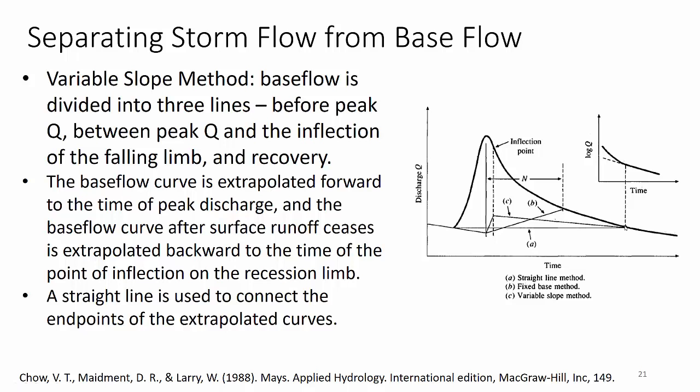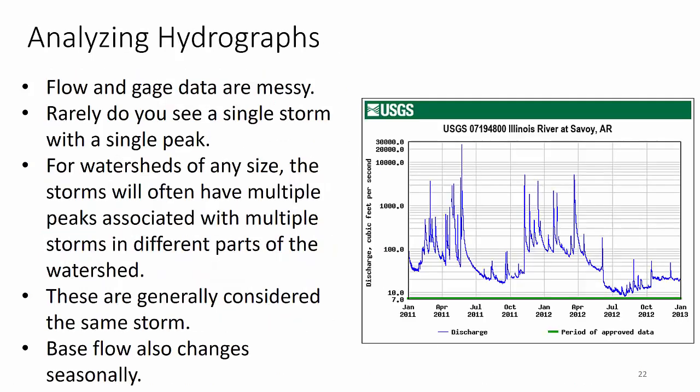This just digs into the amount of runoff you're getting, and I think you could adapt this just by moving it. This is why the straight line method they're showing here really isn't what we normally do. We normally would put the straight line back up here somewhere. They all give you the same volume under the curve. And that's the most important part: how much water ran off during that event.